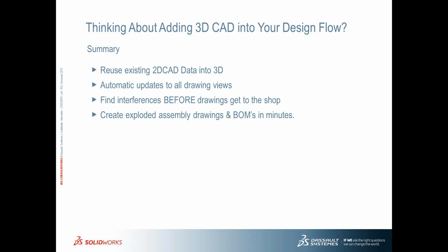And Dan, as I mentioned earlier, with our drawing changes, if I needed to make any changes to that assembly and add or remove components, your bill of materials actually gets updated automatically throughout that process. So you don't ever have to worry, again, about your drawing being out of date from the actual 3D model. So if I sub in a part that isn't in my assembly, that will automatically update in my bill of material. Exactly. You don't have to remove a line item and then re-enter a new line item for the new component. It'll automatically go ahead and make that change for you.